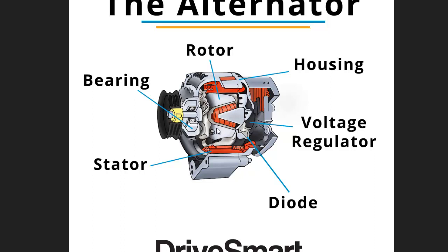So the torque, as we explained in the last video, is equal and opposite less losses. Now if it was perfectly equal, we'd get to a point one day where we could no longer turn the rotor. The rotor itself would stall because of the forces. You've got to remember it's equal and opposite less losses, and that's why the force, the torque, if you like, on the shaft must always increase as the load increases. Same with a transformer, same with a generator, they're all the same.